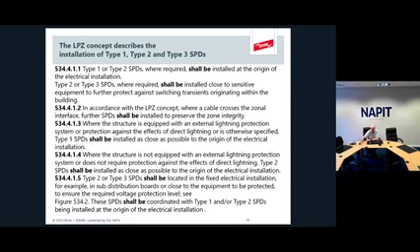themselves. By the way, if you're working in the domestic market, you've got an external zone 0 and an internal zone 1, and that's it. Houses don't tend to have further screened rooms, so you're not going to have subzones normally when you're looking at domestic dwellings. So that's nice and simple.